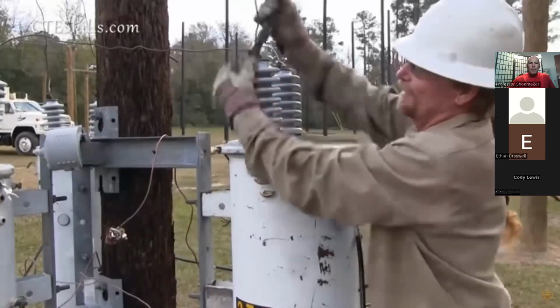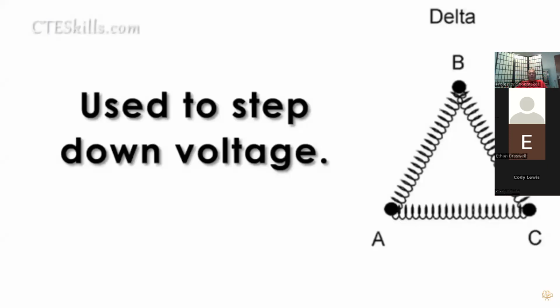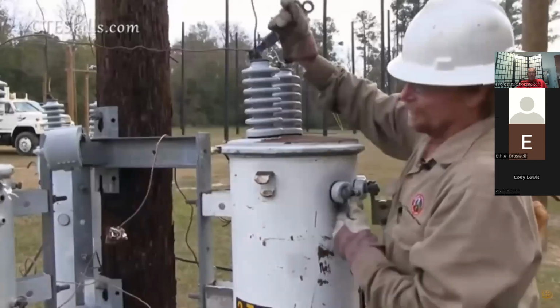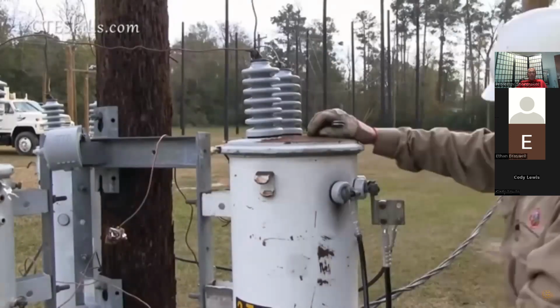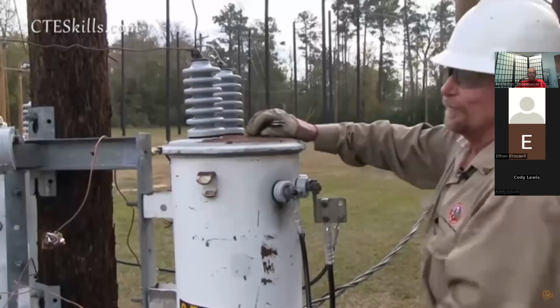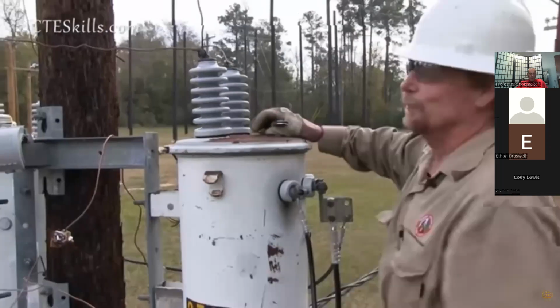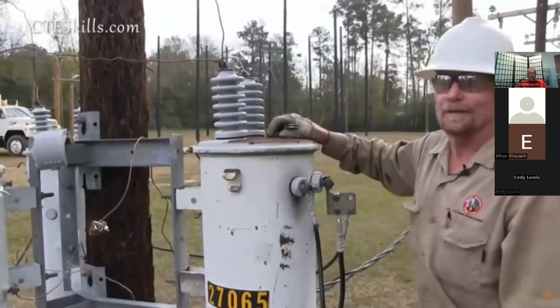The primary side, or the high voltage side coming in, we'd call a Y system, anywhere from 2400 volts up to 19,000 volts. That's what we bring in. We have to step it down. We use the transformers to bring it down. This is what we call a delta system. This is what we call a 4-wire delta. It has three phases for power. We use 2 for lighting. It's a real common type of connection.